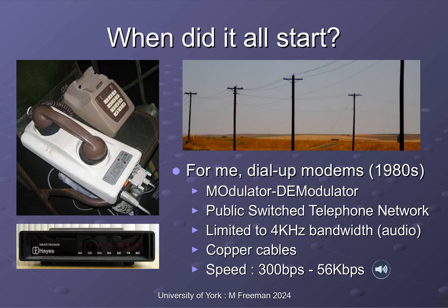To represent our voices, obviously if you're from a hi-fi background, you'll know that you're typically looking at 20 hertz to 20 kilohertz. It's the full range of frequencies the human ear can hear. But as we will see later, to maximise the number of signals we can send down these telephone lines, we need to limit the bandwidth, the frequency range used to represent the human voice. So typically it was around 4 kilohertz, a few hundred hertz to 3.4 kilohertz. So we lost some of that range.